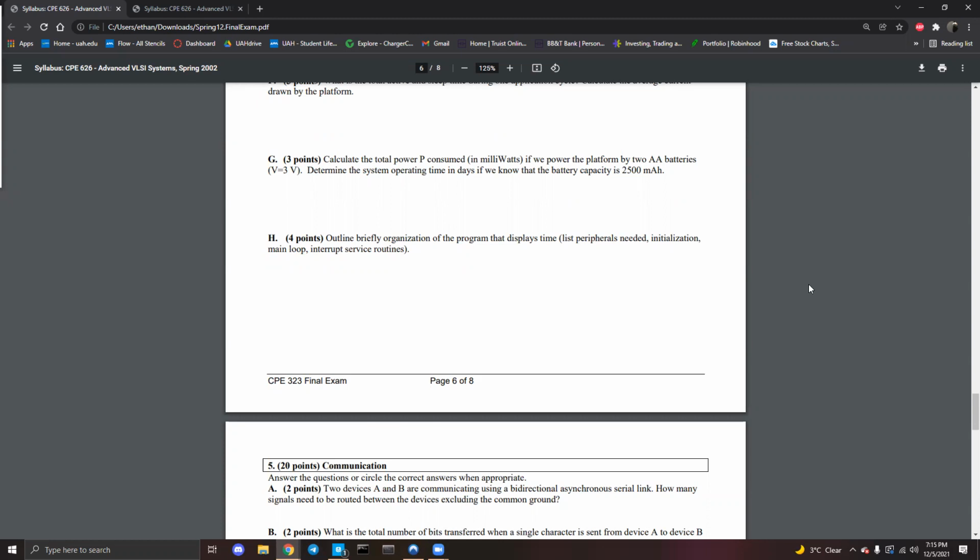Then you are going to need to make the timer A ISR since you're updating the values on the LCD, and you're going to need local variables to hold those values. Then just do a main loop where you enter low power, an interrupt occurs off the timer, wakes you up, you update values, go back to sleep, and do that forever until your batteries run out. It's a bunch of nested if statements for the ISR.